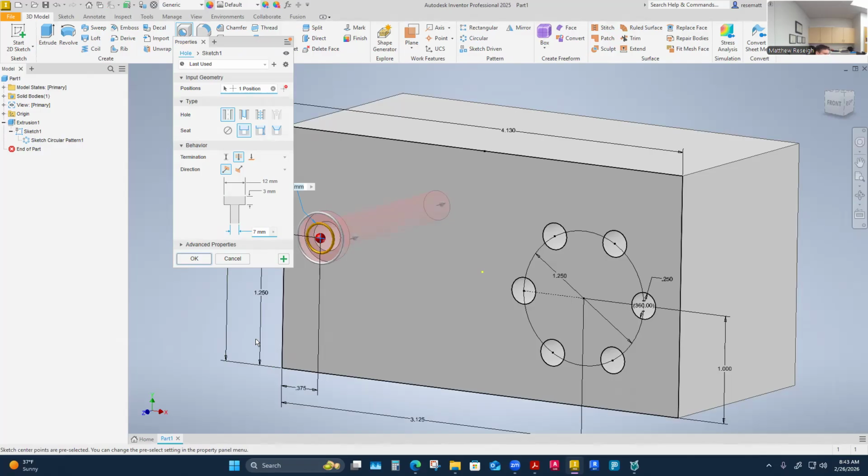It's usually the last thing you use, which looks like I was using a counterbore last time I used this command. I just want it to be a clearance hole, with no seat, no counterbore, no countersink. So no seating. It's just a clearance hole. That's that first one, simple hole. Then there are threaded holes and tapered tapped.